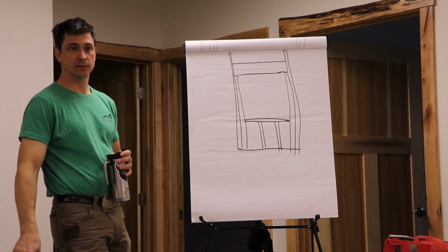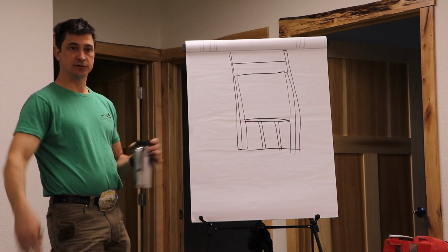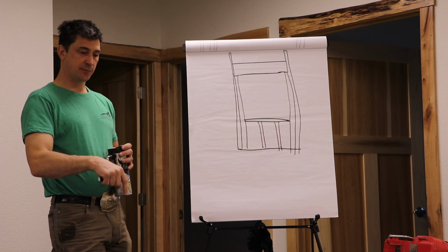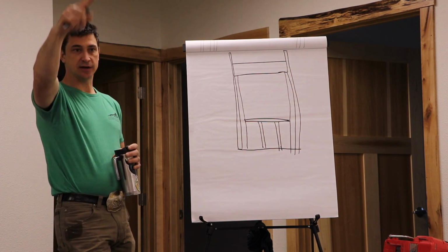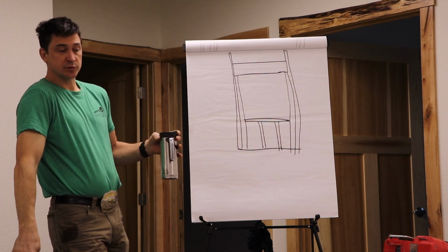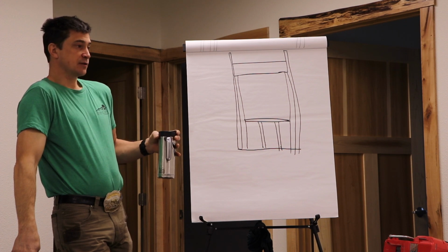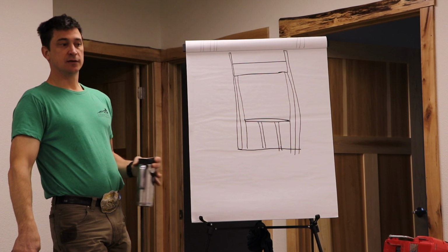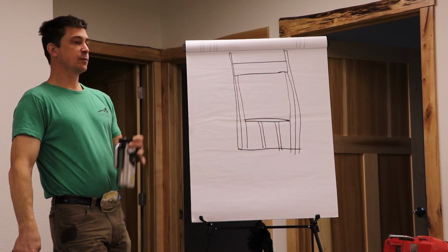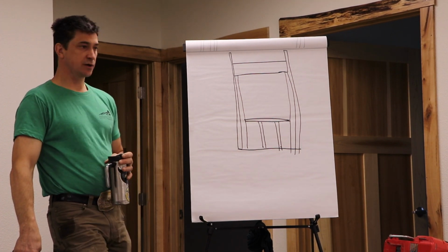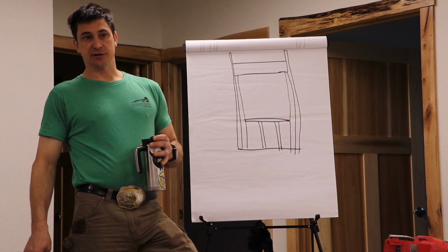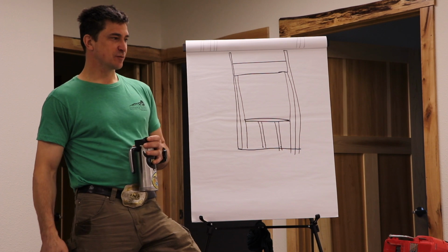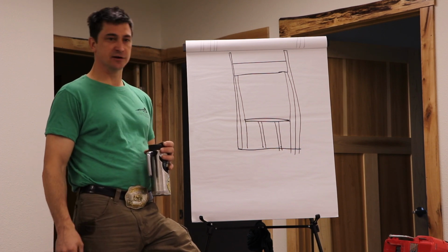Why would he have to go into the crawl space? Because he's not drilling through the wood. If you have all this wood and you can't get a drill bit to go through it, the only option is to go down into the floor joist cavity and up and around. And they'll do it because it's their job to get the house wired. But let's try to make our framing and our construction work for everybody on this project, not just like, oh, we're doing this T&M, we're gonna throw as much material in as we can and make this take as long as we possibly can.